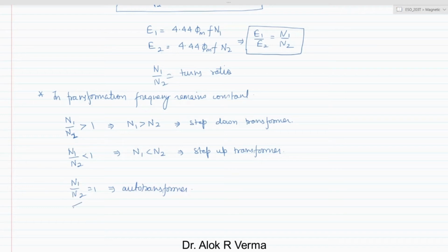In these kinds of transformers, where electrical isolation is required, or we need to separate one part of the circuit from another part for the sake of protection of some element or component, we use isolation transformers. So in case of home inverters or stabilizers, we use a 1:1 isolation transformer in general, which provides safety to the element.